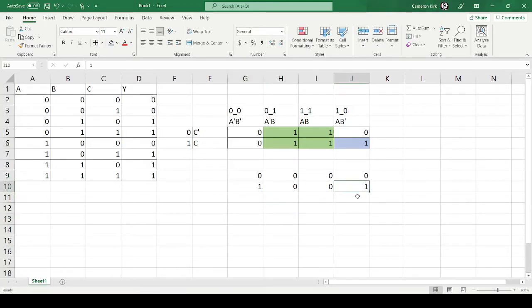But these guys can be grouped together. And again, this is why it's nice to draw, because the tables wrap around. It's kind of like Pac-Man. As you come to the end of your screen and try to walk off of this map, it actually loops around and brings you into here. So if you want to go to the cell to the right of this one, you pop over here and you're in this one. Technically the wall of this guy is touching the wall of this guy, and you can actually make a circle and group these guys together.